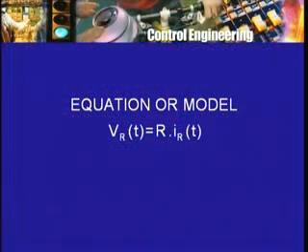Now if this resistance is say heated up, either because of heavy current flow in it, or you keep it near some other source of heat, then will it continue to be described by this equation V equal to R I with R equal to 1.3 into 10 raised to 3, or if I cool it, if I put it in contact with a very cold mass of ice, let's say, will it continue to have a resistance of this same value? As we all know, this is not the case. The resistance value of a resistor will depend upon the temperature of the resistor also.